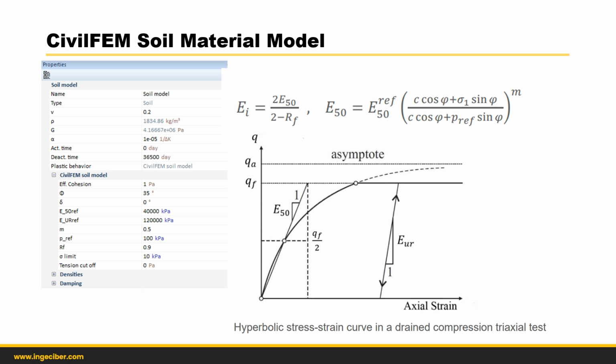The CivilFEM soil model is an advanced model for the simulation of soil behavior. As for the Mohr-Coulomb model, limiting states of stress are described by means of the friction angle, phi, the cohesion, C, and the dilatancy angle, psi.